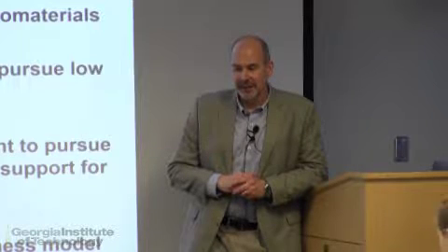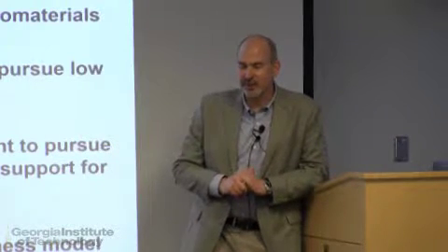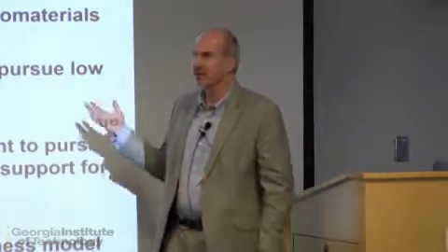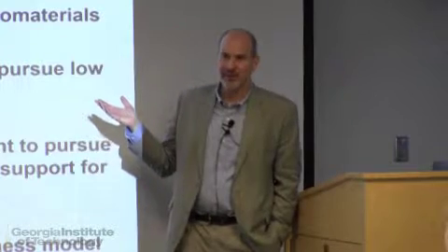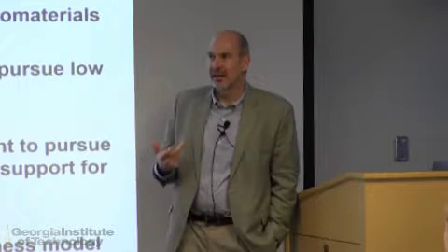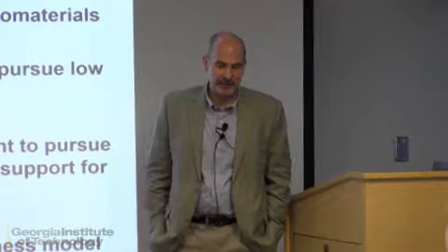I think laser sintering is a little bit harder because you have to be able to mill and process the material. It took us a long time to find somebody who could mill PCL because it's very ductile. If you use mechanical means, you sort of squish it. So you have to use liquid nitrogen jet milling on it. You need technological development not only in the 3D printers, but in the processing techniques you use on the materials to prepare them for 3D printing. So I think that's as much of a bottleneck as the 3D printers.